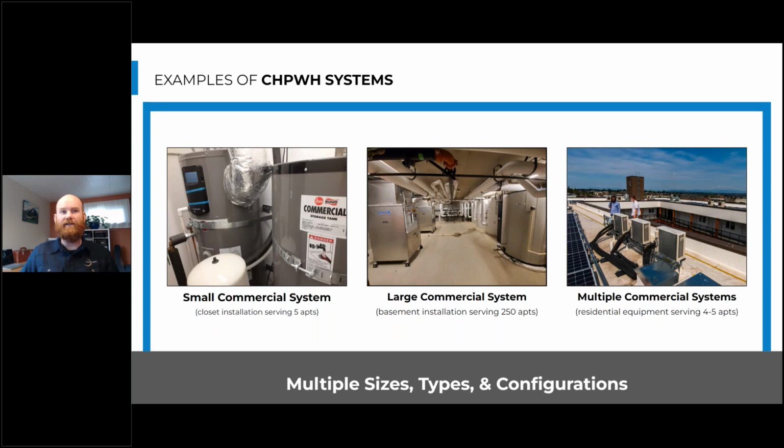So we can operate these heat pumps year round if we put them in an enclosed but ventilated parking garage and put them low down. So there's a lot of that great earth contact, and get some essentially geothermal effect out of this system. But we can also have smaller commercial systems using these integrated products, and we can combine 2 of them together, or maybe a storage tank to extend that thermal battery and serve a bigger load. We can locate these in a closet, but we need to duct them if they're in a closet. So there's some considerations there.